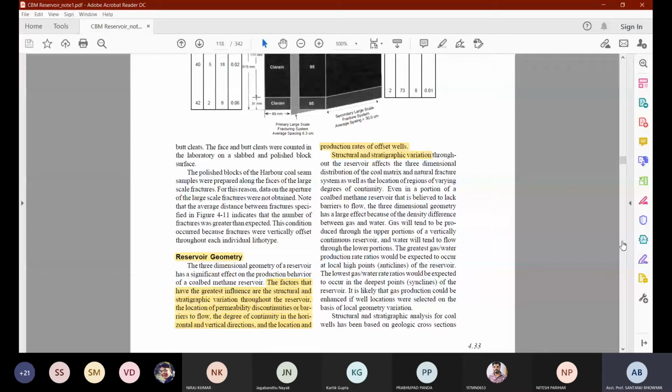Whenever you have seen this type of phenomena, you will be clearly able to understand that if you drill a borehole, obviously the drill-induced fractures are going to create some new fractures in different directions. Suppose you drive a vertical borehole, then obviously you are creating a direct open channel in the vertical direction. But what is happening in x and y? Obviously there will be some radial cracks, some radial fractures, and it is not always possible that radial cracks will be created perpendicular, just the way you have seen in the hydraulic fracturing process. It will not be perpendicular always.